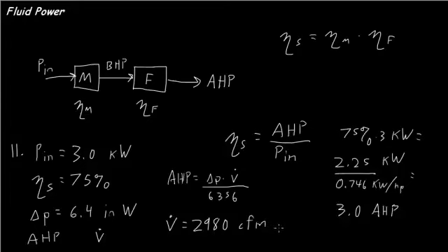So notice in this particular example, I didn't know anything about the brake horsepower or the motor efficiency or the fan efficiency. I went directly from power in to air horsepower using the efficiency of the entire system.